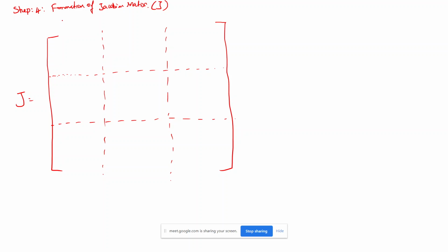Here this is for FP2, the unknown corresponding equation, and this is for FP3, again the unknown corresponding equation, and this is for FQ2, the unknown corresponding equation. Here the unknown values are del 2, which I need to find out, del 3, which I need to find out, and then V2 we need to find out from these equations.